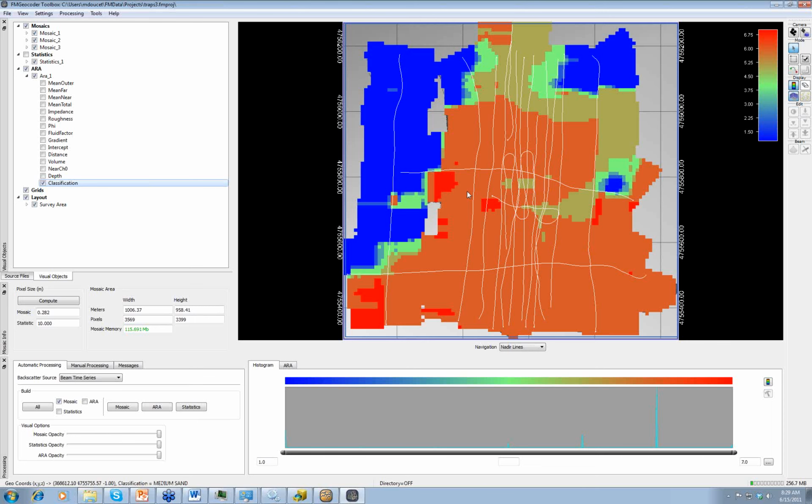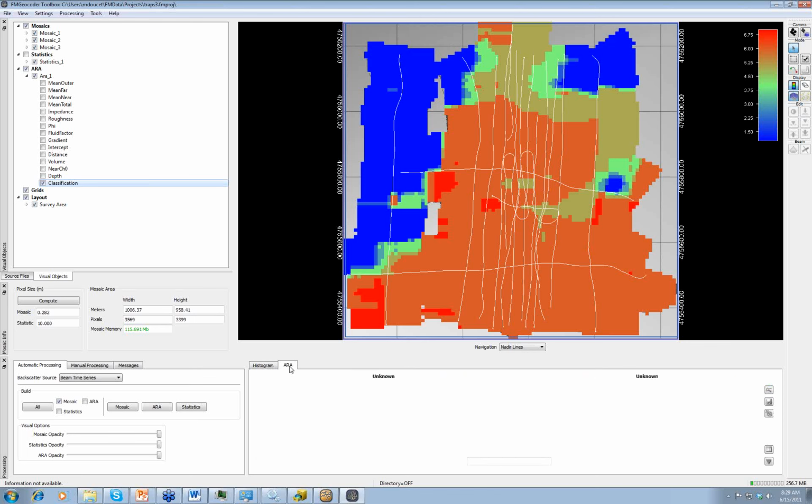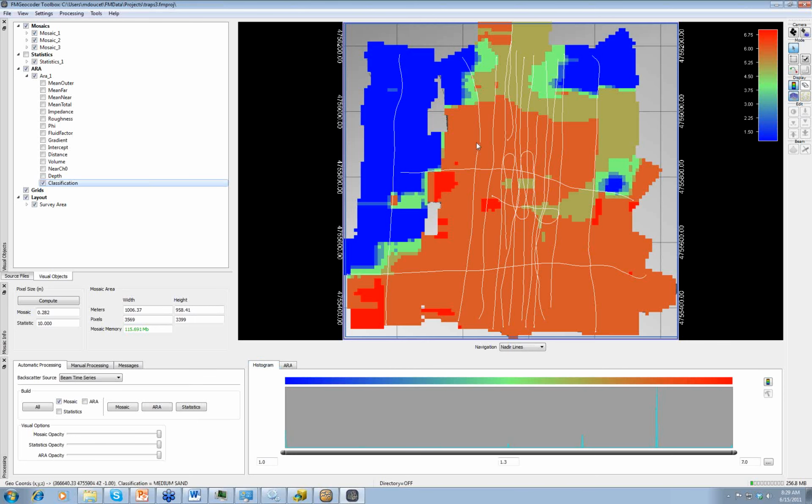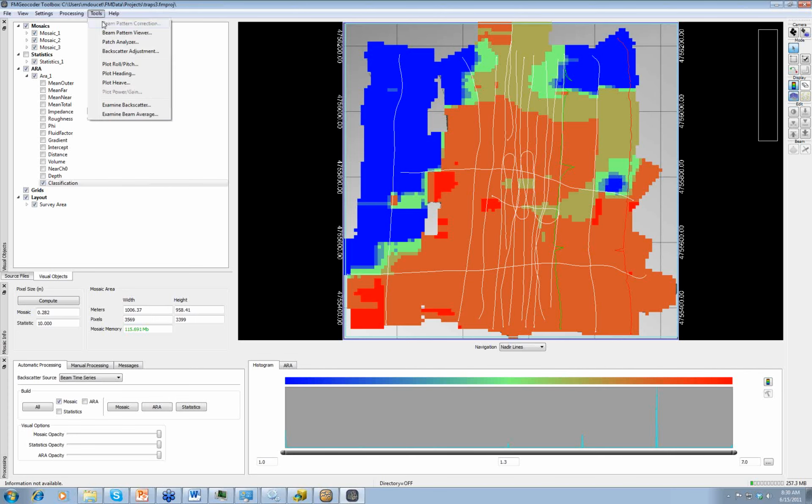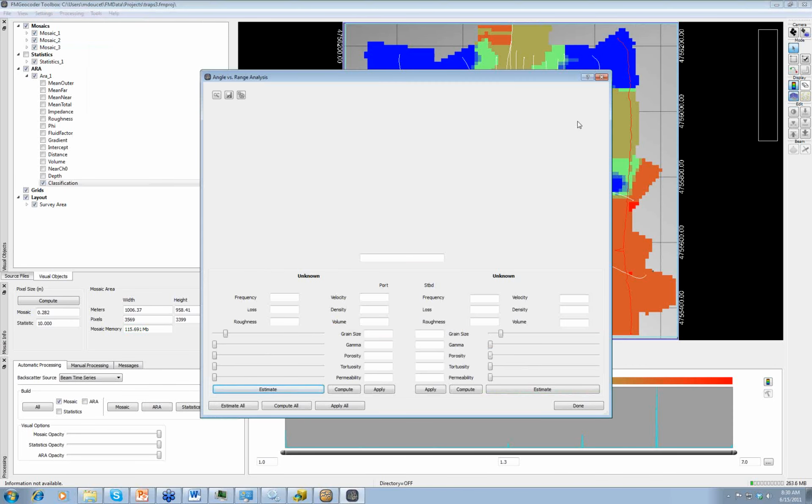Then you measure the data, see what waveform you have, and try to make a match of those two and say the measured waveform looks like the waveform that this set of physical parameters would generate. To me, that's doing a characterization of that match and trying to say this is what your sediment type is. The reason I prefer that over classification is classification to me is having a jar of different materials and saying that one I can observe, it's clearly sand, and this jar here has a bit of clay in it.